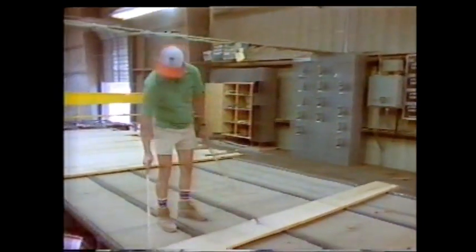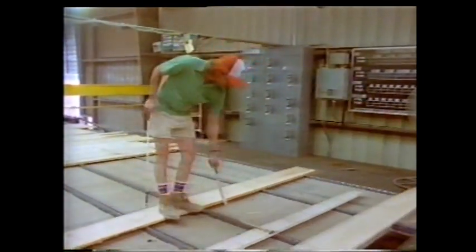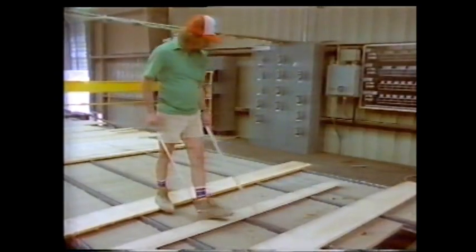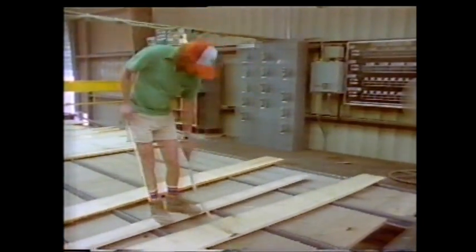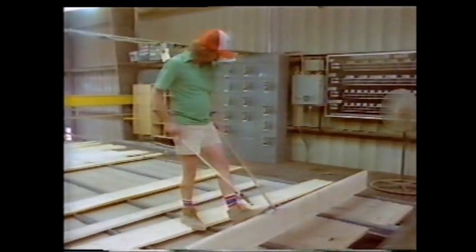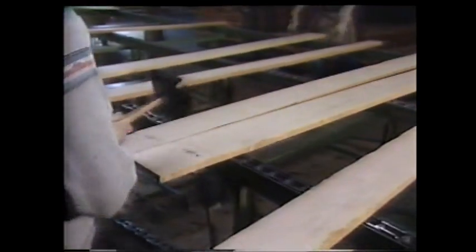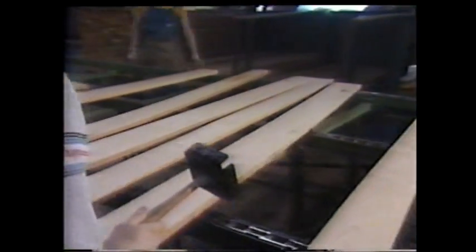With some exceptions, hardwood lumber is graded on the basis of the size and number of cuttings or pieces which can be obtained from the board when it is cut up and used in the manufacture of a hardwood product, such as furniture, flooring, or interior house trim. Common usage generally requires that the cuttings be clear wood, so that the undesirable defects do not appear in the finished product. Generally speaking, the higher the grade, the larger area of clear material contained in an individual board.